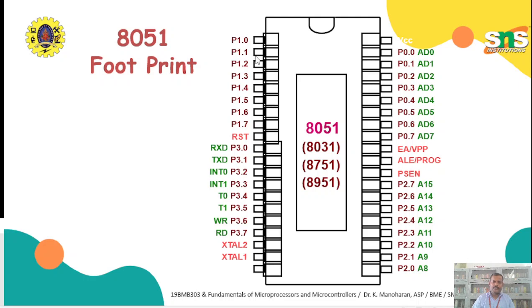Pin numbers 1 to 8 will be mapped with P1.0 to P1.7, and this is pin number 9. Then the next 8 lines will be mapped with P3.0 to P3.7, also with the multiplexing signals. Then the crystal connections, these are pin numbers 18 and 19, and pin number 20 will be connected to ground. Look at this side, P2.0 to P2.7, pin numbers 21 to 28, which will be multiplexed. The next 3 lines are program store enable, then the ALE signal and external access. So this will be mapped. The highest pin number 40 is mapped with VCC.